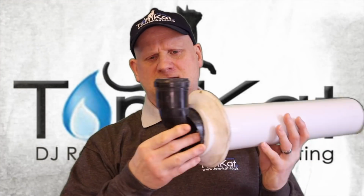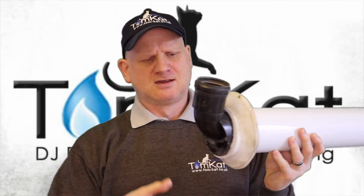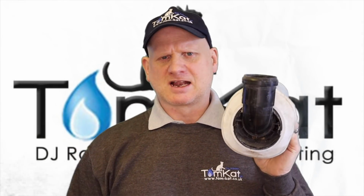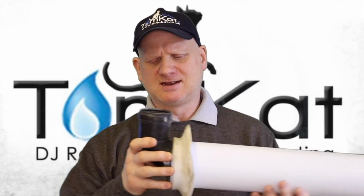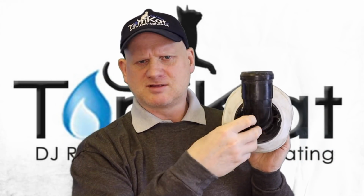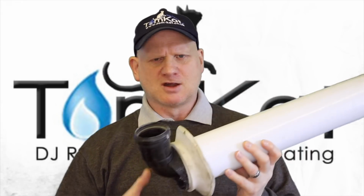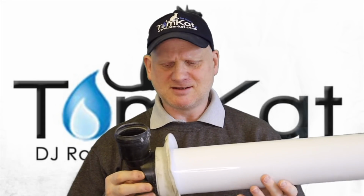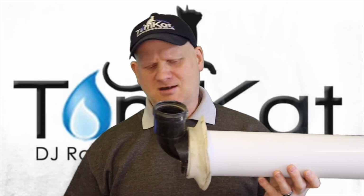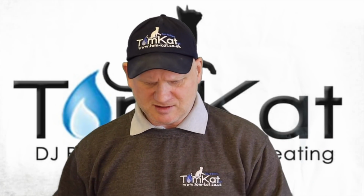Now, this is the standard Glowworm plume management kit, and this front part on the old version used to clip in and used to cause problems leaking, but they've changed their flue system now, where you're just taking the terminal off and plugging in the elbow. So again, they're not standard, and you can't use a Glowworm plume management kit on an Ideal boiler. You can't do that.